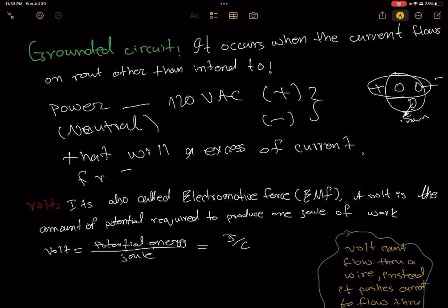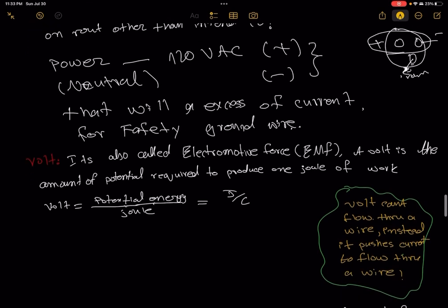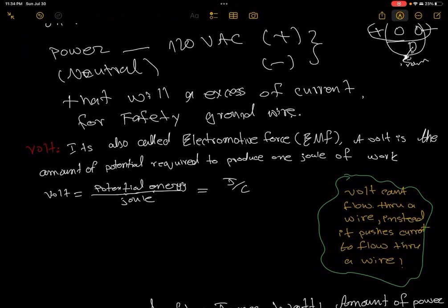Ground wire in a machine, or even in the three-way prong that we have in our house. 3 prongs: one is hot, one is neutral, one is grounded. Never ever cut that third wire, which is the ground, from any machine, equipment, or simple receptacle.